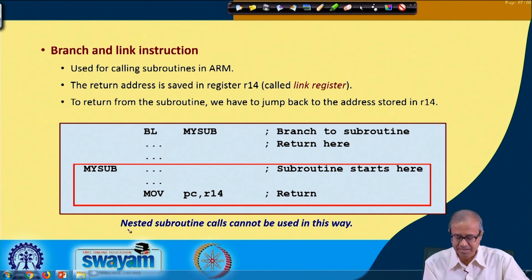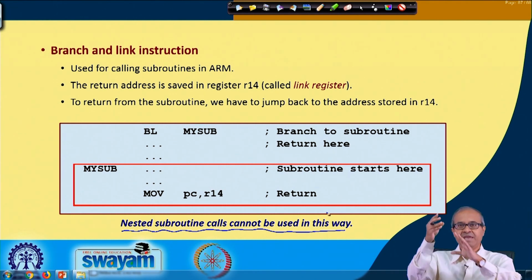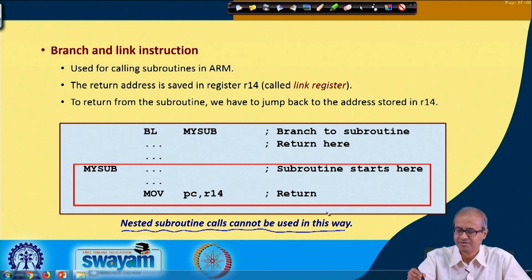But it is clear that in this way you cannot implement nested subroutine calls or recursion, which is so common. For example, subroutine A calls subroutine B, which calls subroutine C. Here you have only one register, R14, to store the return address. When you call A, your return address is stored in R14, but when A calls B, the return address will be stored in R14 again. So, the previous R14 value will be overwritten, and you will never be able to come back to your program. Nested subroutine calls will not work this way; you have to use some other mechanism.